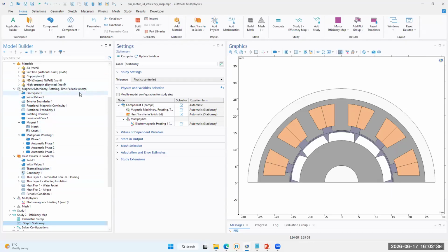But if we use a traditional transient approach, without the time periodic analysis, then I need to use a time dependent study, where it would take time to achieve the steady state, whereas you would be solving the rotating machinery along with heat transfer together in a single go. So you can do a time dependent simulation as well, which might take longer times, whereas this particular interface does it in a short duration with this approach.